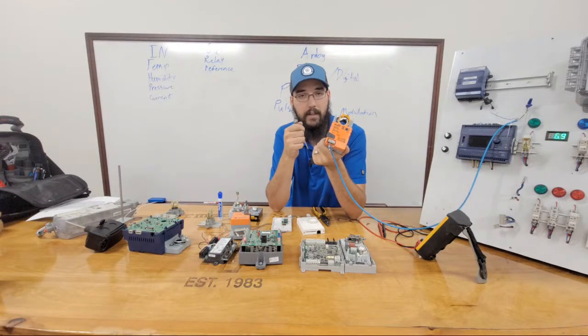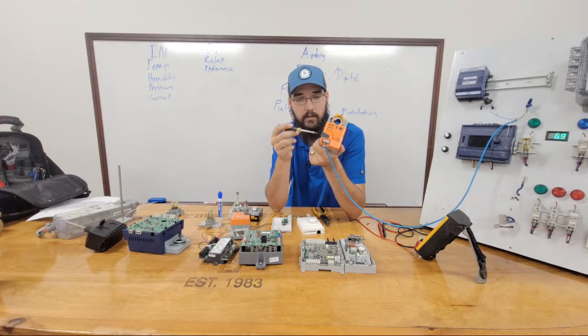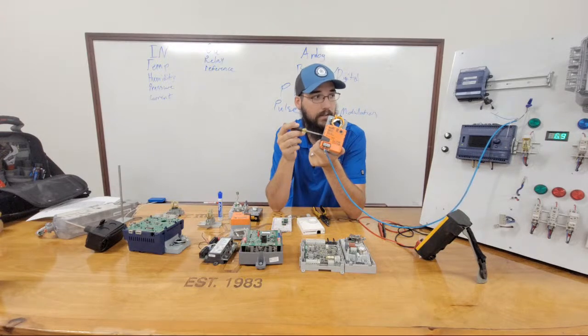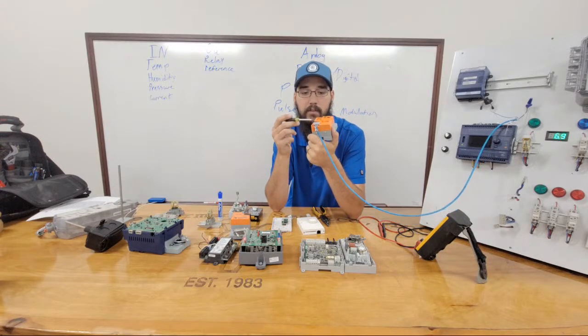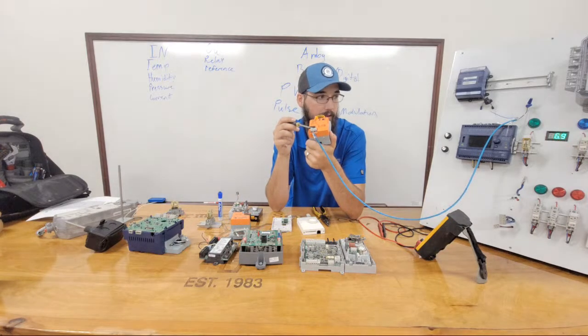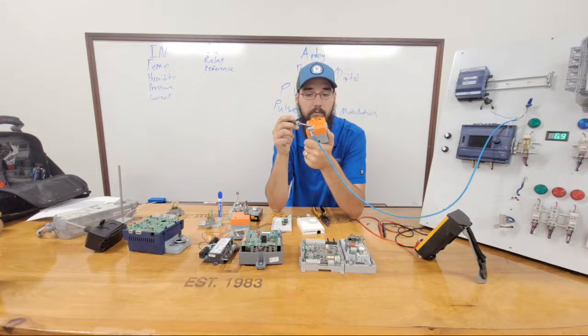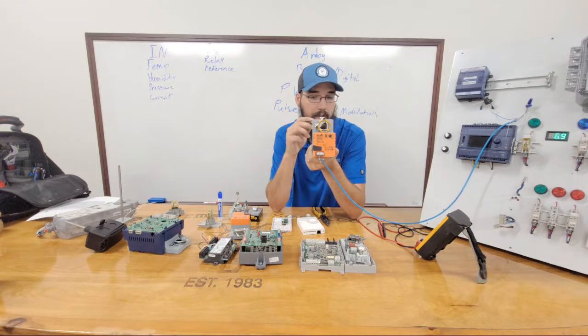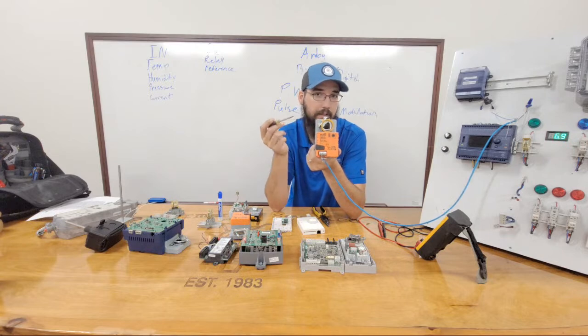If we were able to get that open, there's a legitimate little control circuit in there with a processor that is making decisions based off of how much that input is reading, and at the same time, because you're going to have a constant 24 volts coming to this thing, it is reading its own potentiometer to know what position it's in.